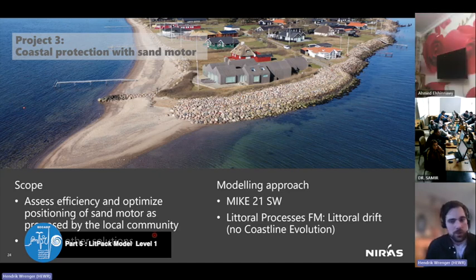And the modeling approach was again setting up a spectral wave model, and then we used the littoral drift from the littoral process FM. In that case, we didn't do the cross-shore profile evolution, and we also didn't use the coastline evolution because it was really outside of what could be modeled with the coastline evolution module, and we will look at why that is in a second.